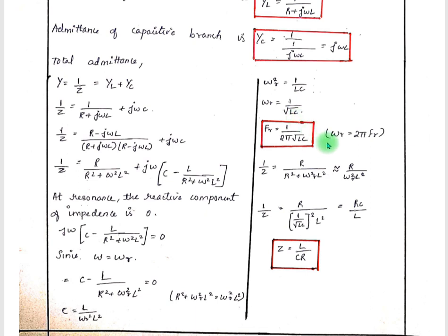We have the value of ωR as 2πfR. So let us substitute the value, and we will send this 2π on the right hand side, as here it was in multiplication form, and after going to the right hand side it will become division form. It will be in the denominator as shown. fR, the resonance frequency, is equal to 1 by 2π under root LC.